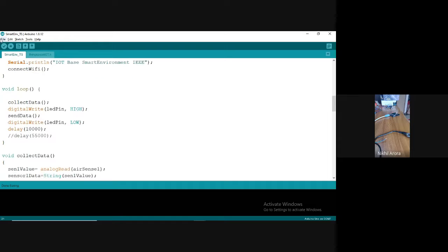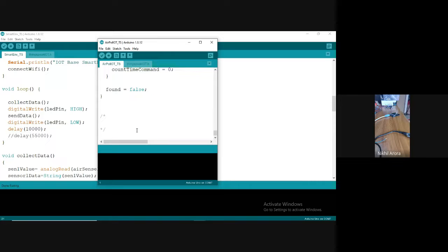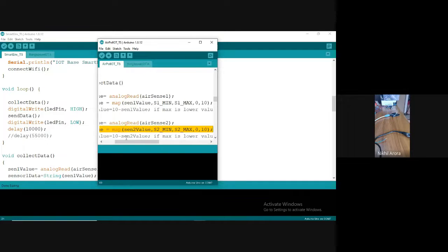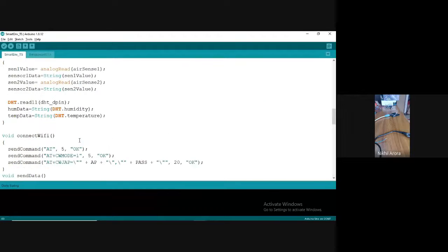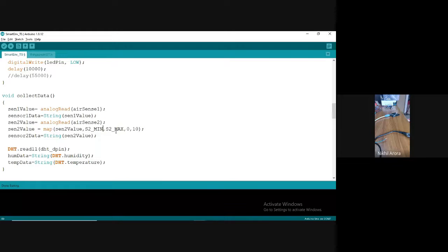And we were having one more thing which we can do now. That mapping. Map function we can use here to map sensor 2 value between HG levels, because HG levels should not go to random values. So we'll map it to some reasonable values. So from 0 to 1023, you make it something like 20 to 100. So this will be the range. These numbers will be converted into these numbers, and that only will go as sensor 2 value as a string.